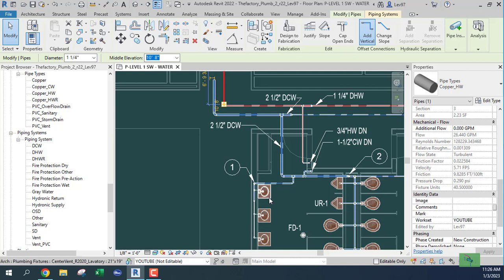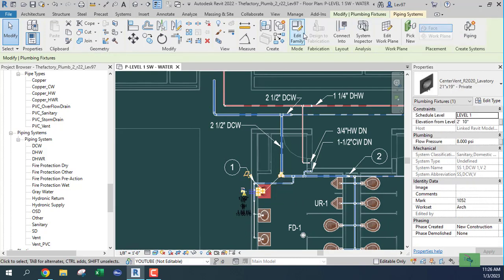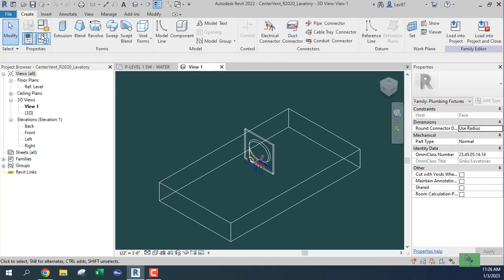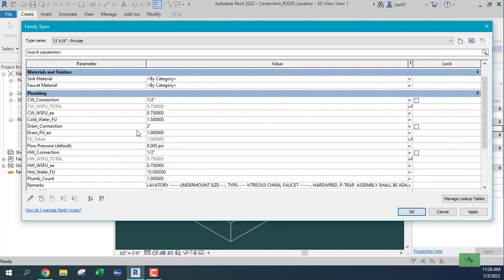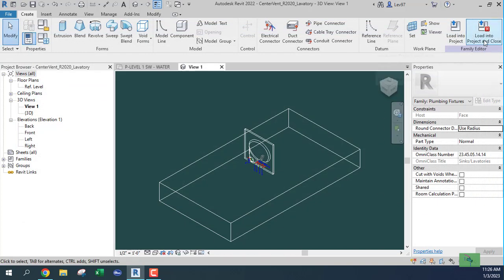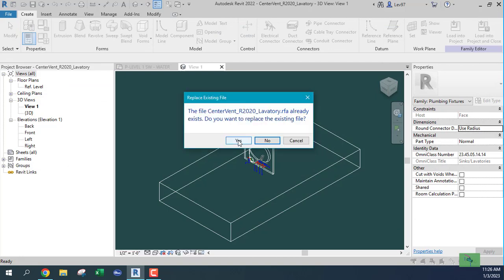So let's do an extreme case and see what Revit does. I'm going to go back and edit my hot water fixture units, because at 188, we know that the cold water side is going to give us about 87 GPM, right? Which is what Hunter curve is telling us. So let's make an extreme case. Hot water fixture units, what did we use? 25, 35, let's use 50 fixture units. Let's get up into the curve and see what Revit is going to give to us.